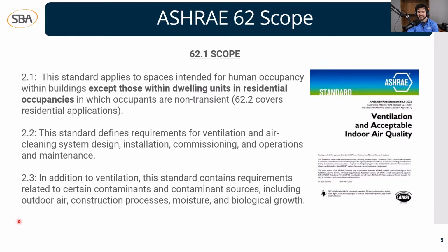And honestly, this is where a lot of projects go sideways. I've been on a lot of jobs where the design met 62.1 perfectly. However, the dampers were installed backwards, or the filters weren't replaced for an entire year. Good indoor air quality isn't just a design concern. It's a life cycle concern as well.